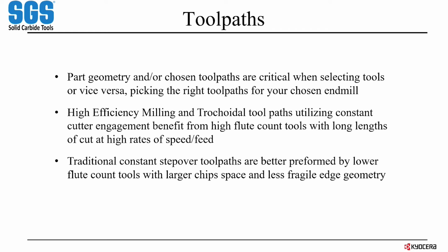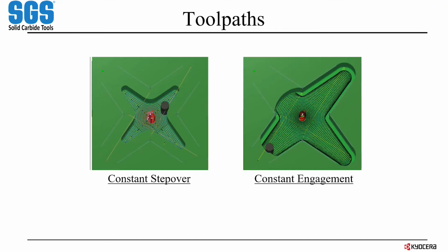And whenever you have spikes in your tool engagement, that can be really detrimental to your tool. So by going to a constant engagement instead of constant step over, you can really control that engagement. Well, you're obviously controlling it, but really you're controlling that heat and that buildup of pressure and preventing those spikes. And so here you can see a demonstration of the two.